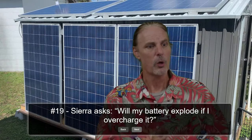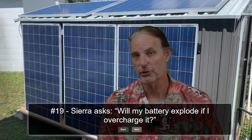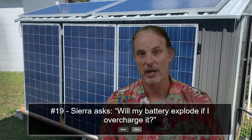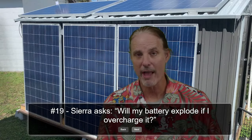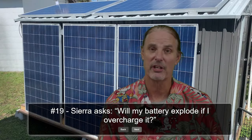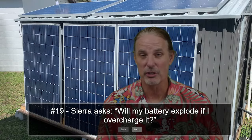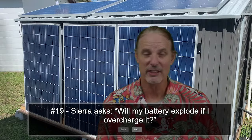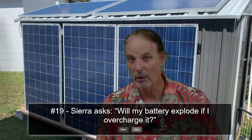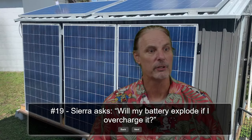All right. Will my battery explode if I overcharge it? If you've got a BMS, it shouldn't. It shouldn't basically overcharge at all. It should shut down before it gets to overcharging. If you don't have a BMS, you're on your own, and I don't know what the cells would do. I have never run a cell to that extent. I don't think they would explode. I think they would melt down and shut off. With lithium iron phosphate, the phosphate makes the lithium very stable and prevents runaway burns and stuff like that. But that would definitely do it.